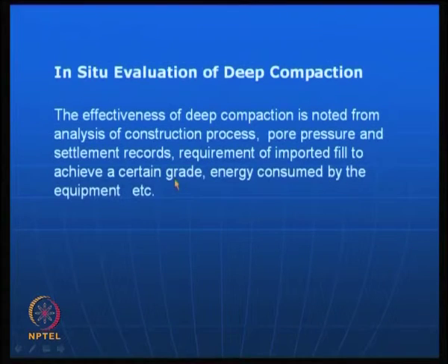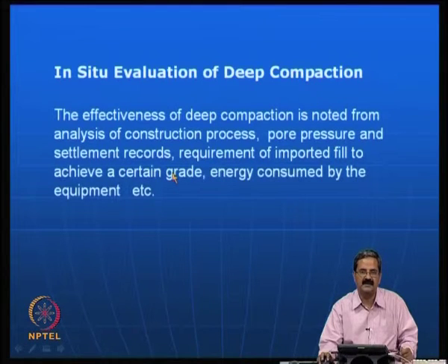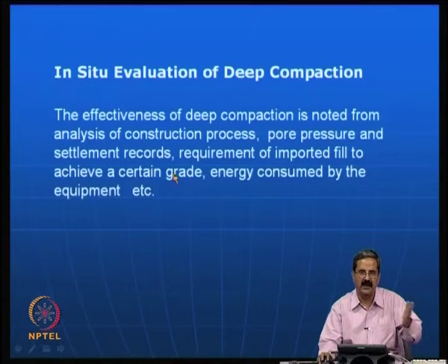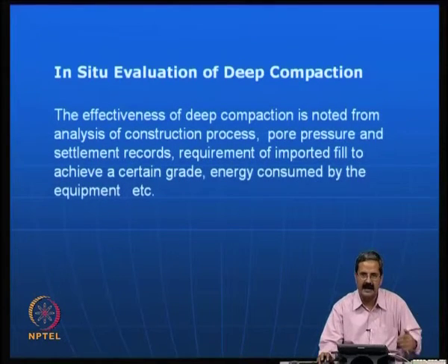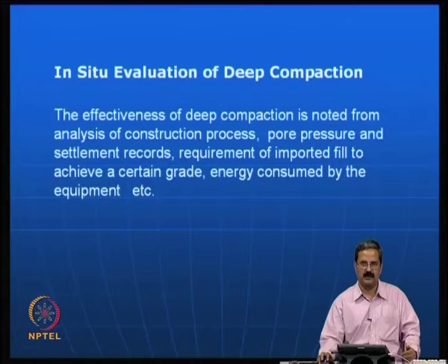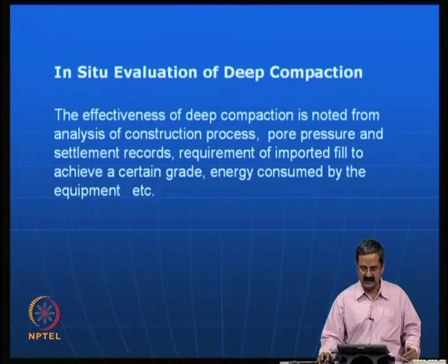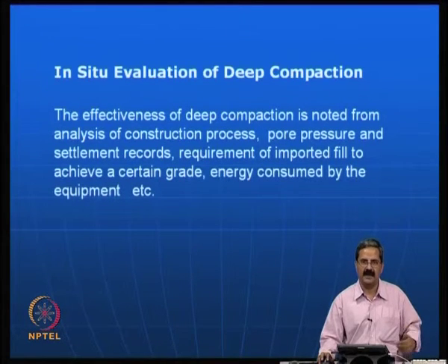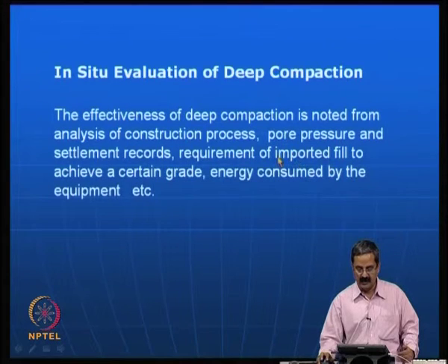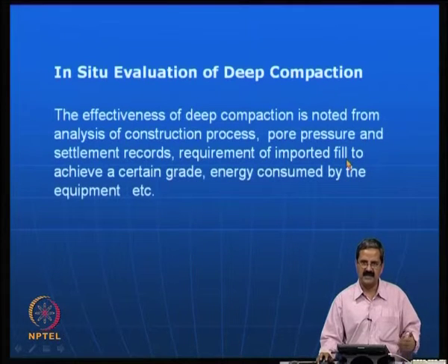Then what we do is check the requirement of the imported fill to achieve a certain grade. Sometimes, in a particular place, the whole area is very soft, so you bring some other soil from a nearby island and try to densify it. In some places, for example Singapore, as I just mentioned, and other places, you will see some more examples here, you have to get soil from somewhere and start compacting. In this process, you have to really check if the imported soil has the required properties, like whether it has achieved that density or water content and all that.